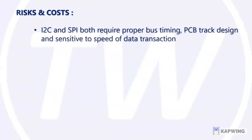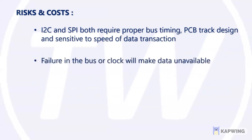Now, when we come to the risks and the costs, what are the risks? I2C and SPI both require proper bus timing. What do I mean by bus timing? Suppose you have a PCB where the bus track lengths are huge, or you have larger parasitic capacitances. In those cases, you have to discuss with your teammates, or look up the data sheet and calculate the capacitance or the pull-up resistors in order to make the I2C communication work.